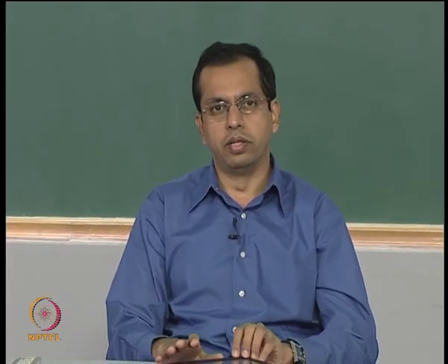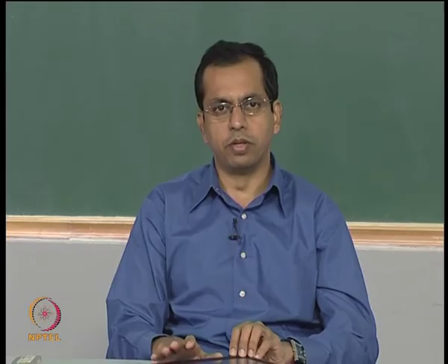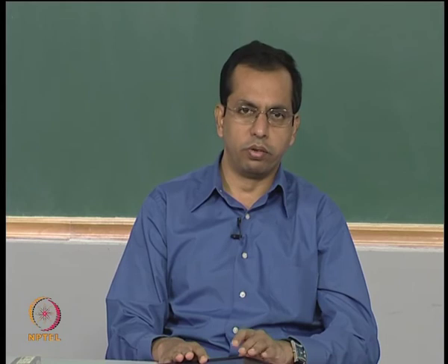What I am trying to do here is to give you an intuitive feel for why we get this omega u by k everywhere. It is not arbitrary and it is not a coincidence. Omega u by k happens to be the unity loop gain frequency for this particular system. So, that sets the bandwidth of the system, and this will be true of every negative feedback system. There may be small changes from that, but the unity loop gain frequency is what sets the bandwidth of the system.